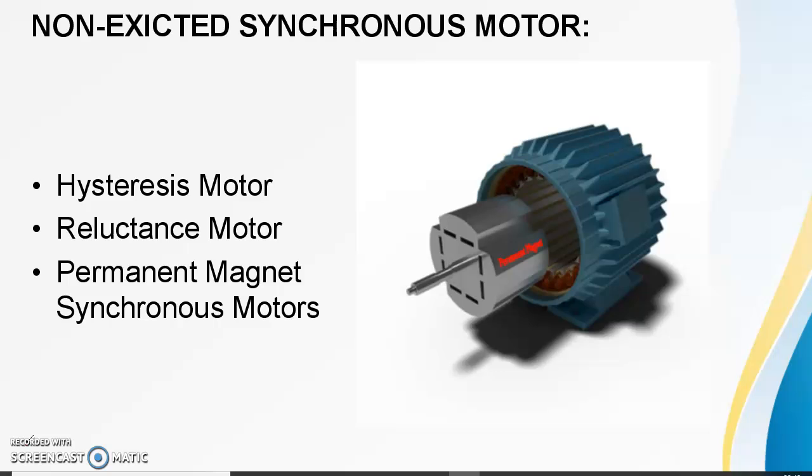A hysteresis motor is constructed of 5 main components: stator, single-phase stator winding, rotor, shaft, shading coil. As there are no teeth and no winding in the rotor, no mechanical vibration takes place during its operation in a hysteresis motor. The main applications seen for the hysteresis motor are sound producing equipment, timing devices, electric clocks.